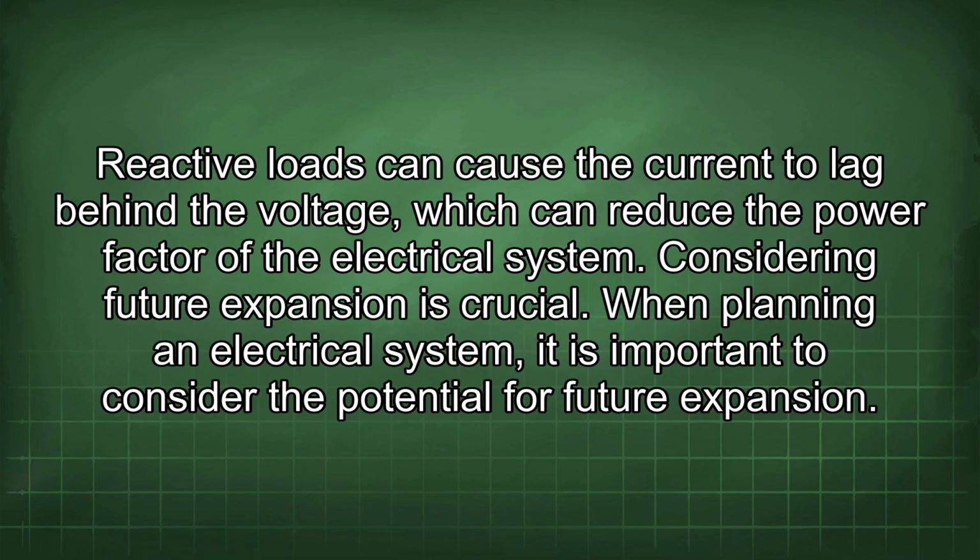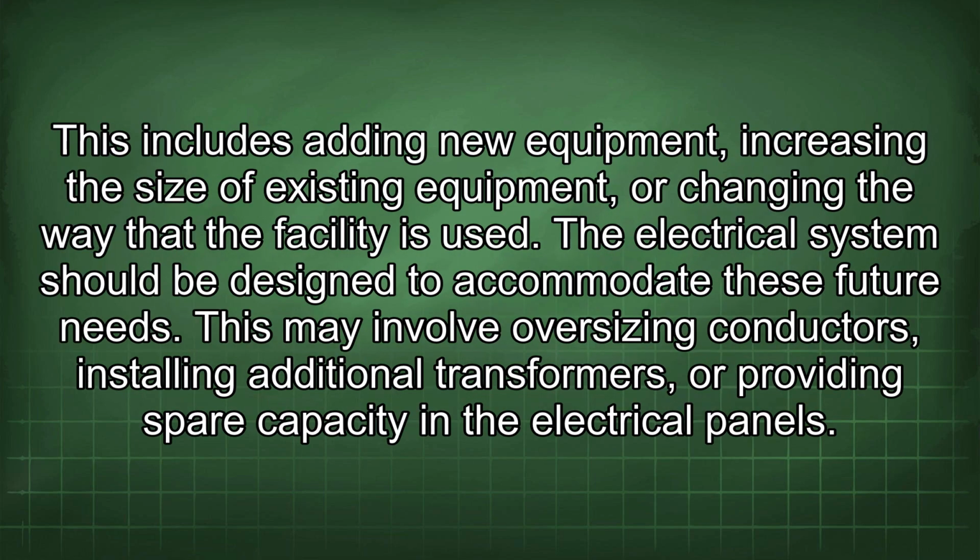Considering future expansion is crucial. When planning an electrical system, it is important to consider the potential for future expansion. This includes adding new equipment, increasing the size of existing equipment, or changing the way that the facility is used. The electrical system should be designed to accommodate these future needs. This may involve oversizing conductors, installing additional transformers, or providing spare capacity in the electrical panels.